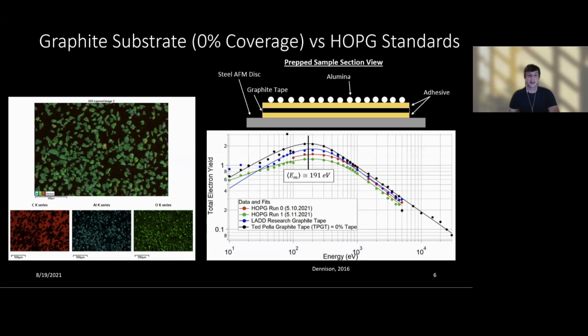So one of the primary technical difficulties is how to even get measurements of granular and highly insulative materials, as they are subject to electrostatically lofting during data collection, just like on the moon. And more importantly, how do we know the uncertainty and systematic errors in the data when there is limited complete comparison data? All these concerns may be addressed by carefully selecting the substrate to which these aluminum particulates are embedded. And our choice was some form of graphite substrate.